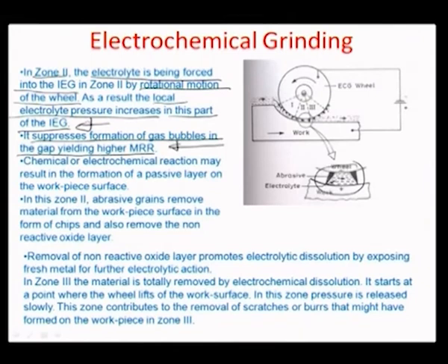because the ambient pressure is already very high, and therefore a slightly higher MRR is desirable in this particular zone, because you are suddenly squeezing the electrolyte into a very small region, thus increasing the likelihood of increase of pressure. So whatever gas has been dissolved from the previous zone sort of bubbles out of the system.